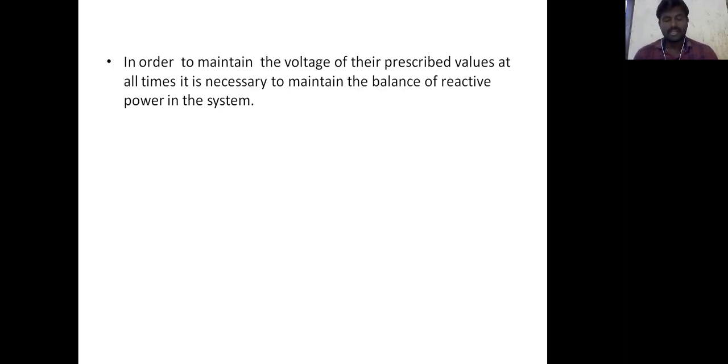If VAR generated is greater than VAR absorbed, the voltage goes up, and if VAR generated is less than VAR absorbed, the voltage goes down. So when the reactive power generated equals the reactive power absorbed, the voltage is flat, the voltage is constant.